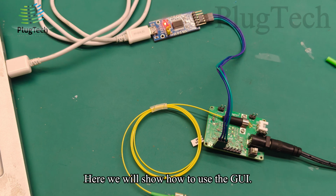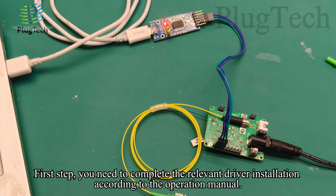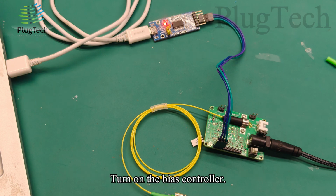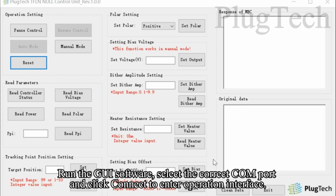Here we will show how to use the GUI. First step, you need to complete the relevant driver installation according to the operation manual. Then connect the bias controller to the computer through a USB adapter board. Turn on the bias controller. Run the GUI software. Select the correct COM port and click Connect to enter the operation interface.